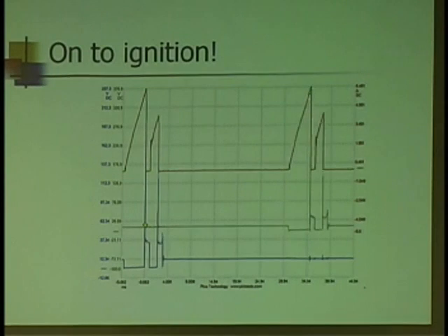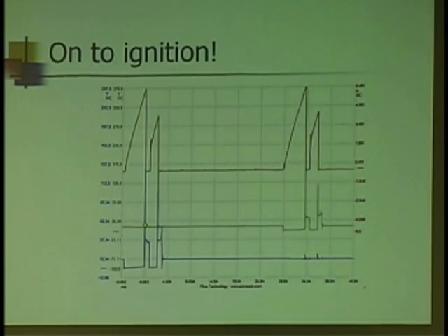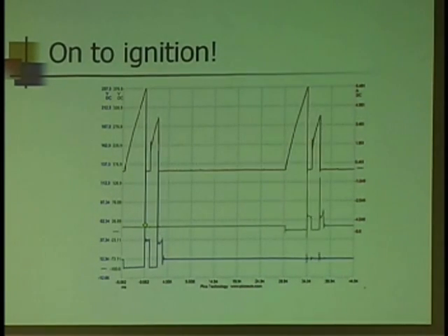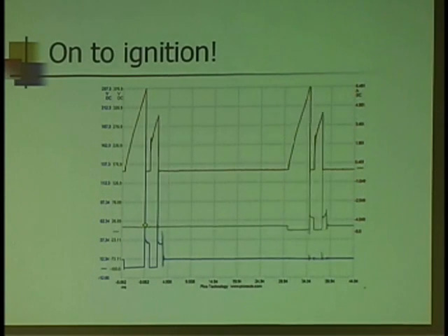Of all the ones that you look at, it'll fluctuate the most because the conditions in the cylinder are never the same. Okay? So what I'm looking for when I'm looking at a secondary ignition waveform is repetitions of an anomaly. What stands out of whack, and I see it often.